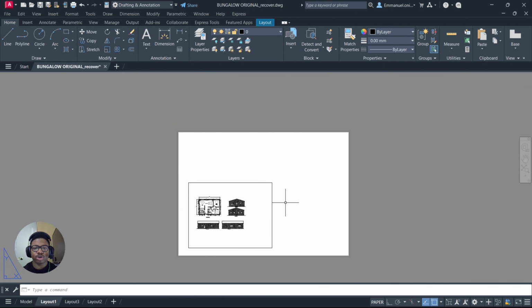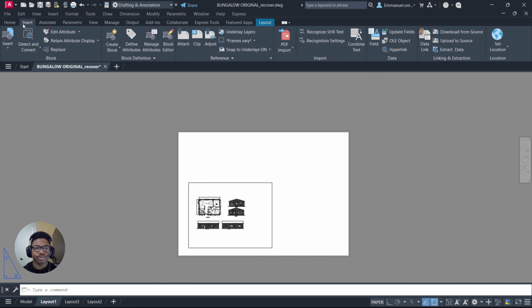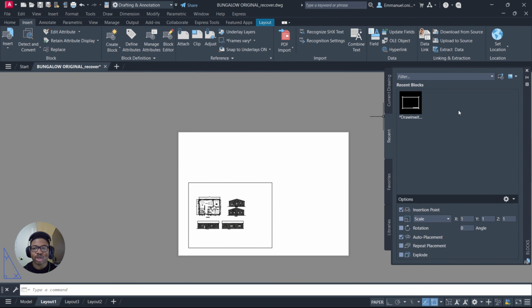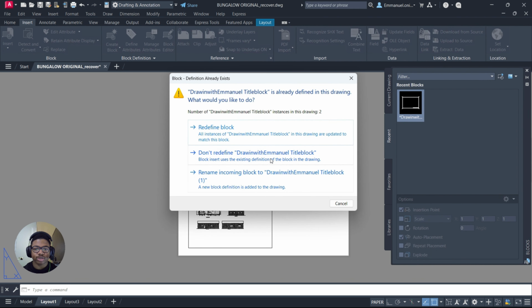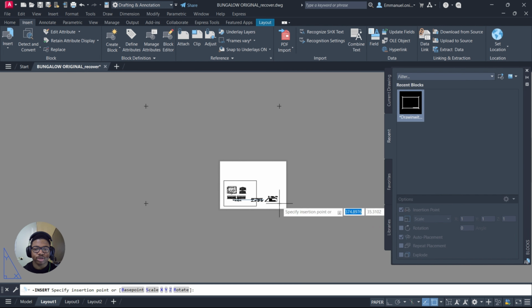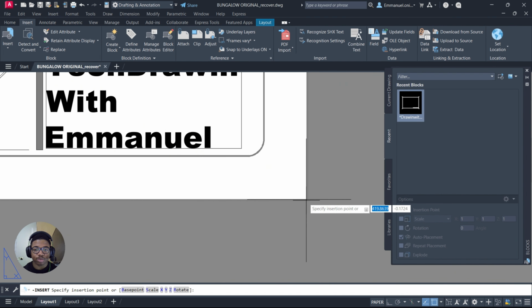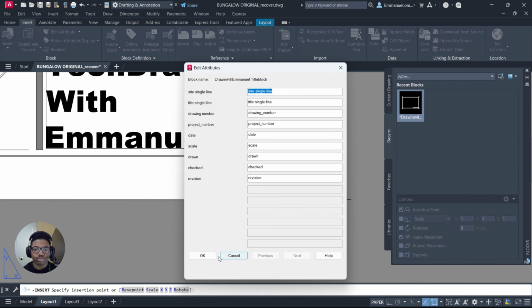So now right here, we have a real life size A3 sheet of paper in our CAD layout space. The next thing we're going to do is go to the Insert tab, and after we get there, we're going to say Insert, and we're going to insert a title block. I have a preloaded title block here. I'm just going to click that in, press Don't Define, and bring it in. I'm just going to click it onto the edge of my sheet of paper. Click it down there, press OK.